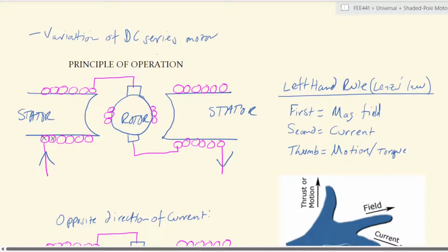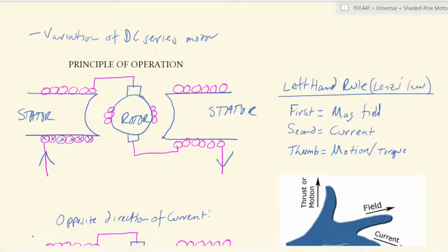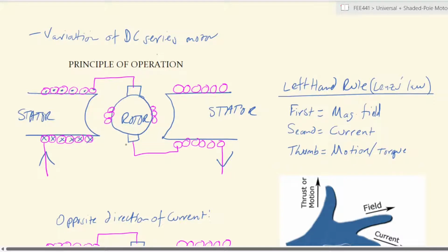And if you have current flowing into them, we can assign a direction of flow of current looking like that, as we had indicated earlier in the unit. This is a direction of current represented by the cross sections of the windings, and in this particular diagram, current is assumed to be flowing into the windings on the lower side of the stator, which means that on the upper side, they would be flowing out of the surface of the screen, right?